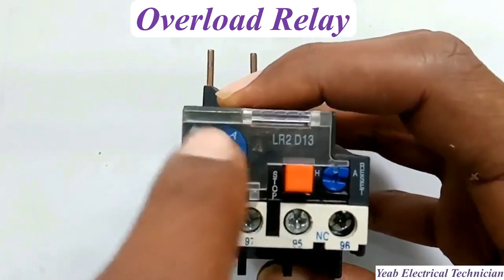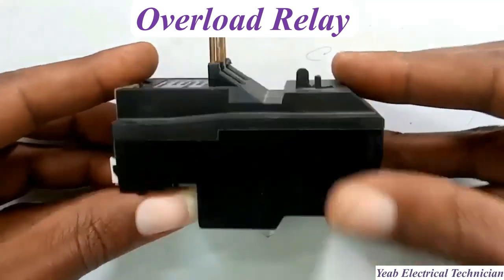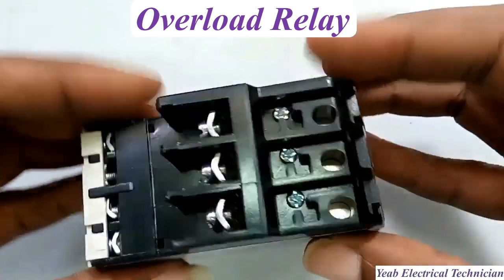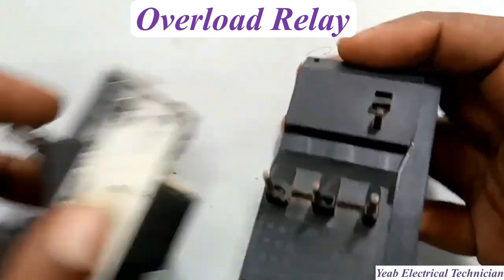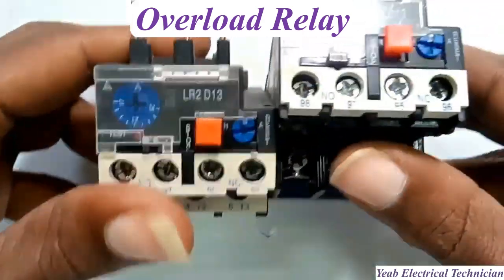Overload relays also protect against issues like phase loss or imbalance. It prevents the motor from overheating and damaging its windings due to drawing too much current for too long. The relay continuously monitors the current flowing to the motor, detecting when it exceeds a safe predetermined threshold.